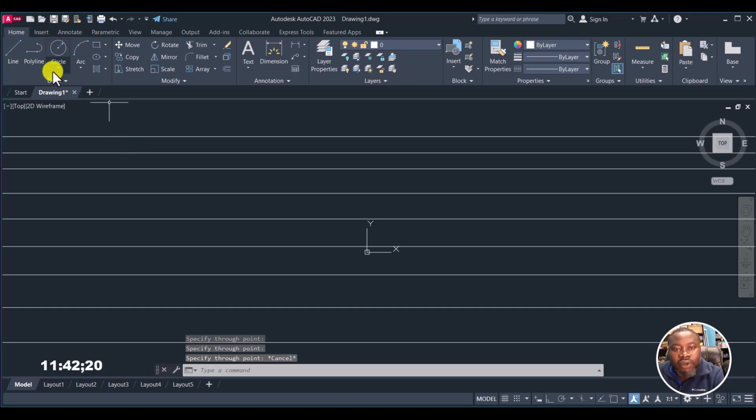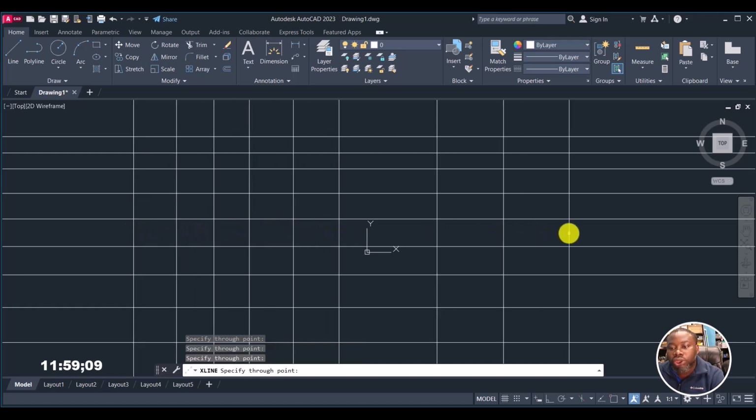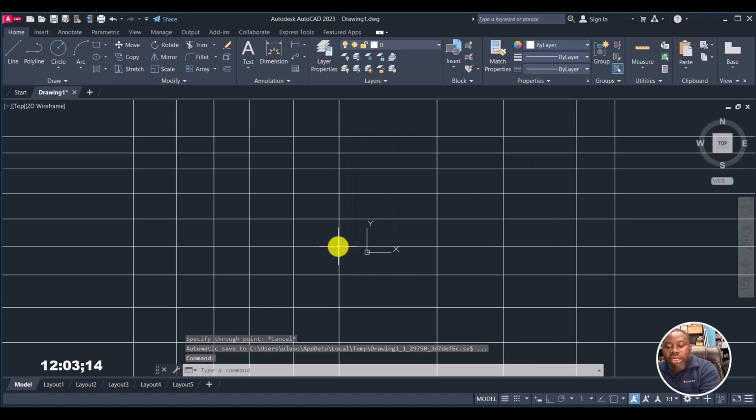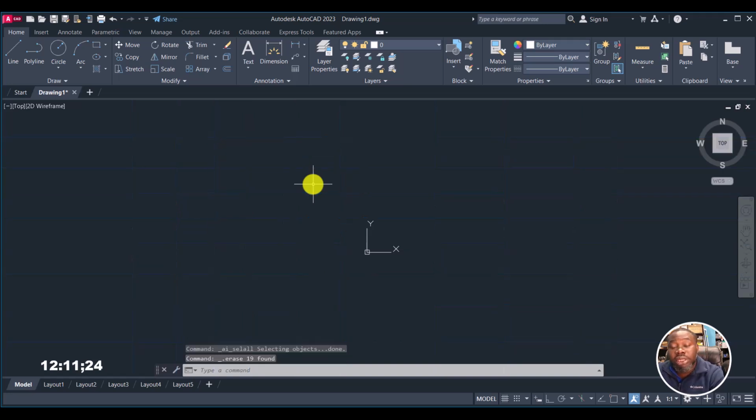All right. So if I want to draw a vertical construction line, it's similar. Construction line. Then I click on vertical here. So it gives me a line without beginning, without end, but vertical. So, all right. So here I have a vertical construction line. I'm going to select everything on my screen by pressing Ctrl A. Then I click on delete. So I'm going to delete everything.